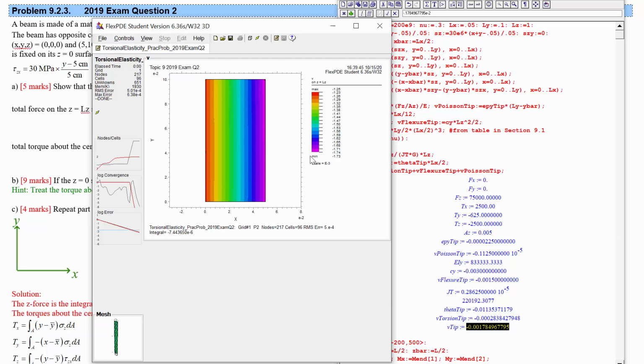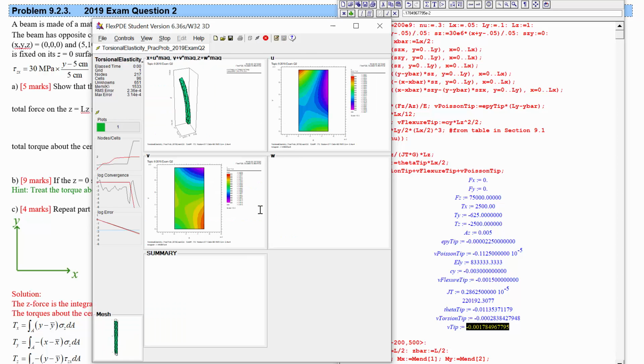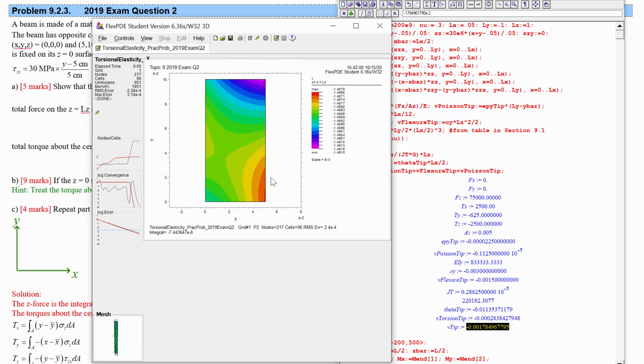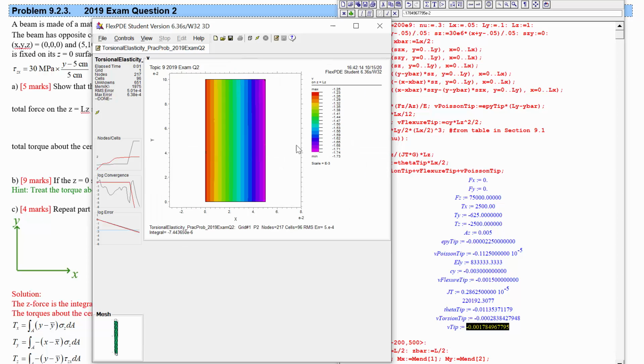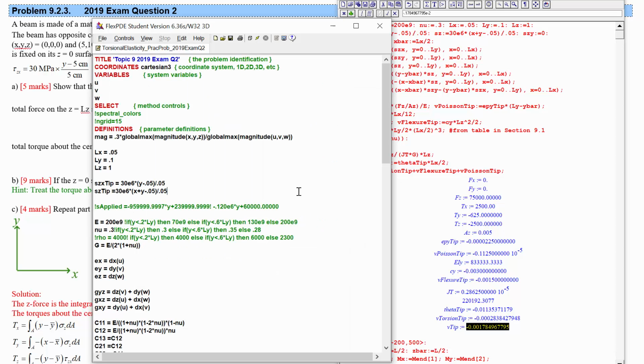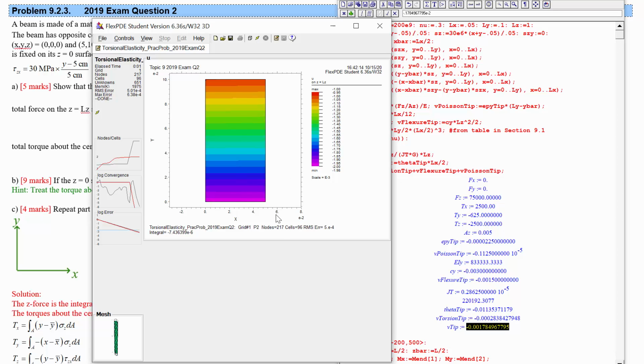If we get rid of the torsional moment, the twisting moment, which was the y dependence here, then that should go away and we've got no positional dependence on y anymore. And we end up with 1.5, which is just basically the flexure displacement. Okay, so that dependence on the horizontal position, what the vertical displacement will be, is due to the torsion. That also is what's giving us a vertical dependence on the horizontal displacement on this end.